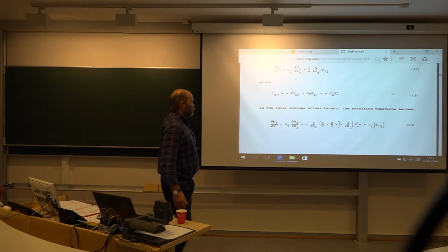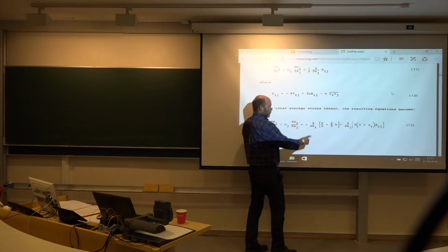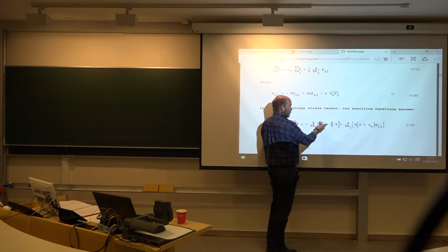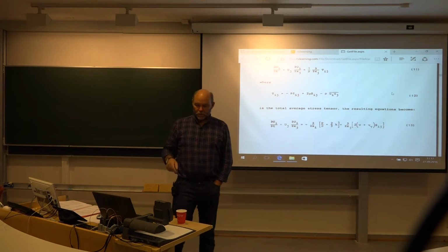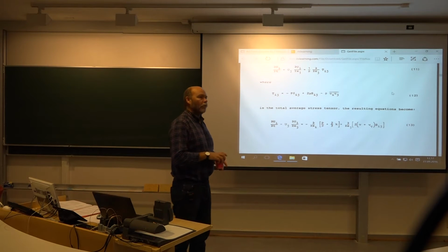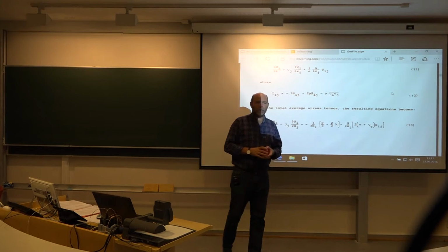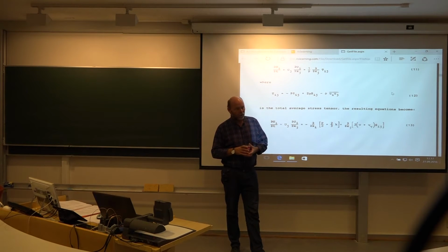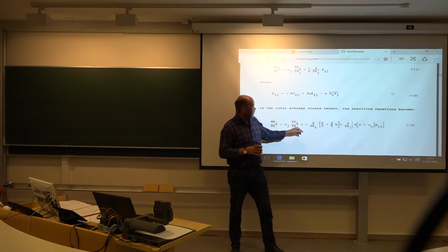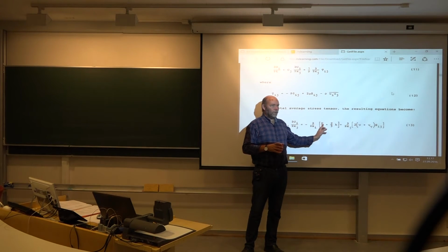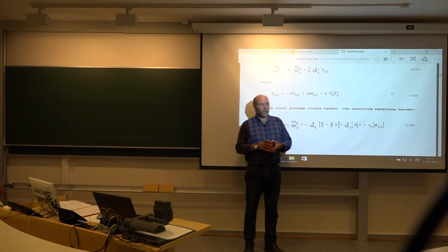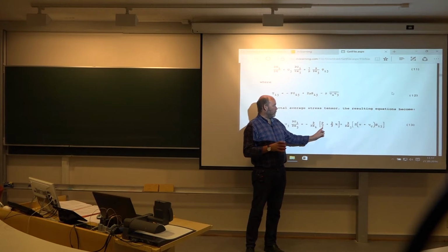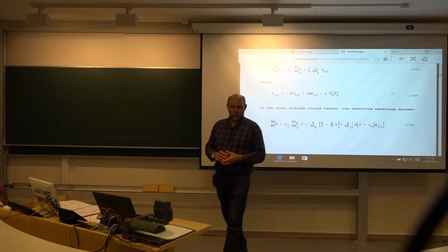First of all, look at the pressure inside this equation now. It reads pressure over density. If you look into the cases you have run so far in OpenFOAM, everybody has been incompressible. And if you look at the dimensions of the pressure, it is not Newton per square meters as you are used to. What OpenFOAM is actually calculating is pressure divided by density. So that's a surprise for you.